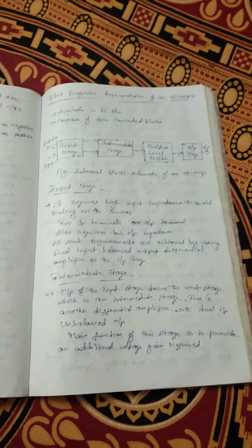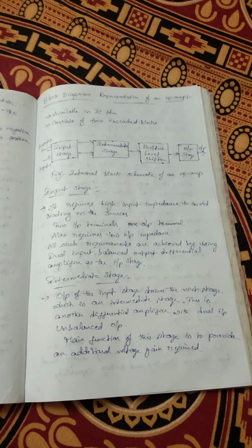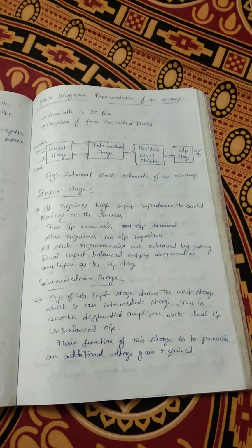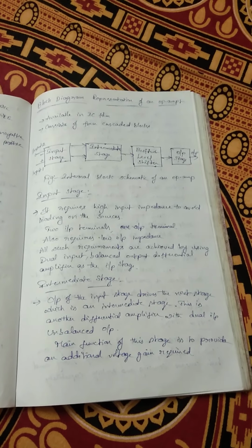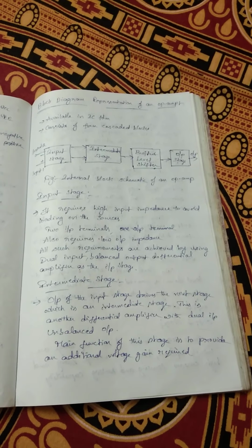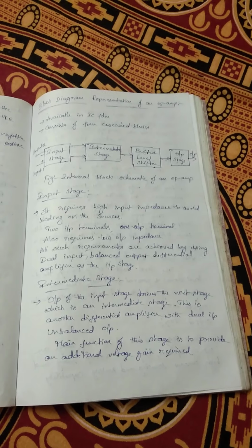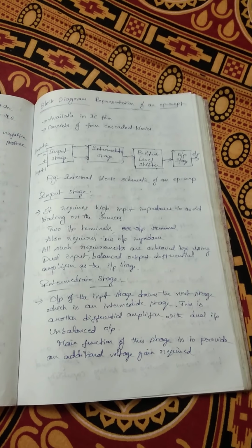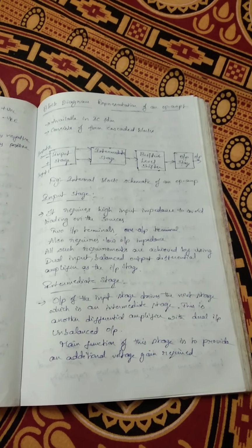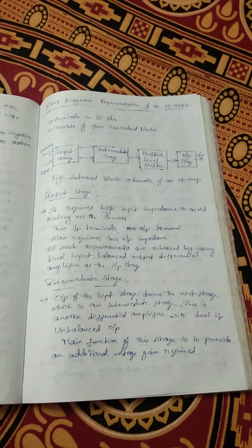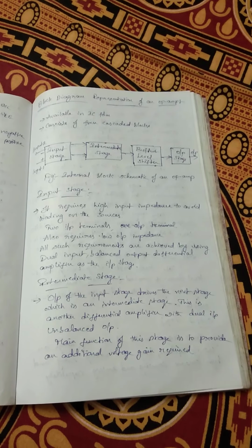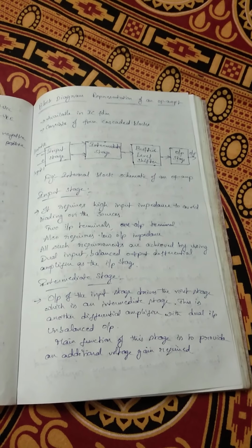Before going to know about the level shifter stage, here all the stages are directly coupled to each other. As the op-amp amplifies DC signals also, coupling capacitors are not used to cascade the stages. Hence, the DC voltage level of the previous stage gets applied as the input to the next stage. Hence, stage by stage DC level increases well above ground potential.